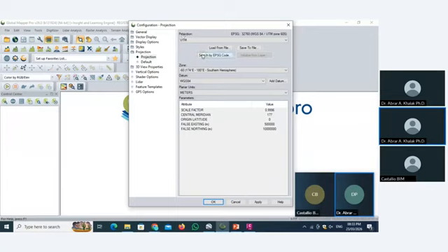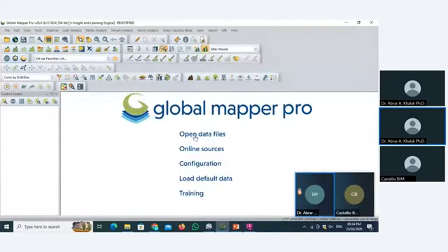Okay. Now as we import our road center line and our OGL surface, we check the zone here, and if there is a difference, we can change the zone here, so we can get the exact point where we work. Okay, apply and okay.